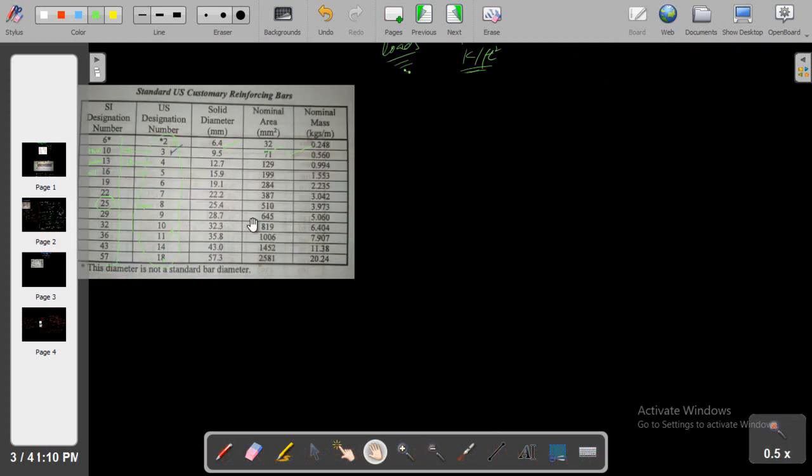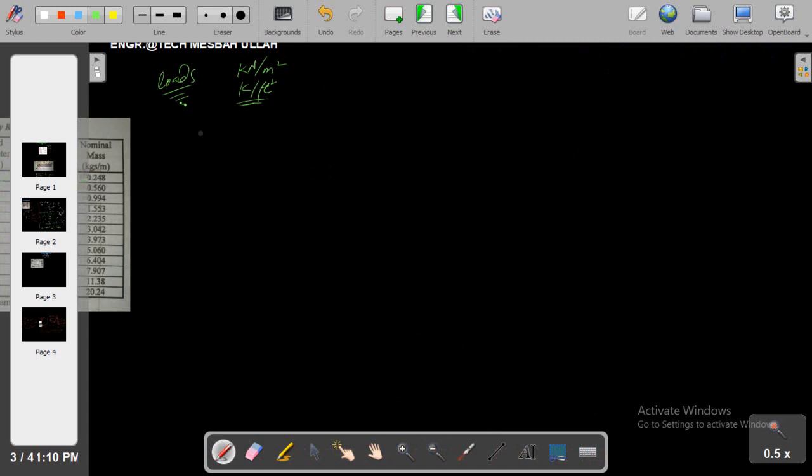So how to calculate loads? This is an important question. Let's say for a slab, because we calculate loads from the slab and then we transfer the slab loading to the beam by using the equivalent tributary area, as we discussed in part 08, right? Either considering the trapezoidal loading or triangular loading, and then converting that triangular loading to equivalent UDL loading. I have already recorded lecture 02 part 8, so please go there and watch that lecture.